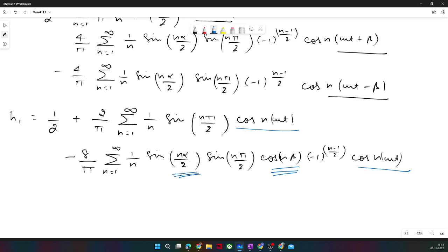So generally in sine PWM, based on carrier and reference, the number of notches is very high. The number of pulses is generally very high. So the reason of getting more terms in the reference of alpha and beta is that there would be multiple and variable references.